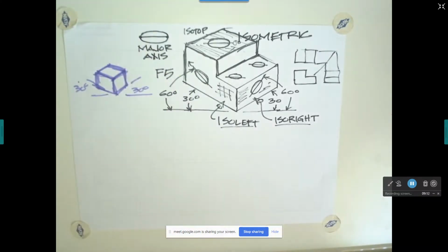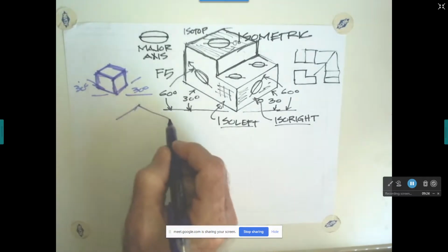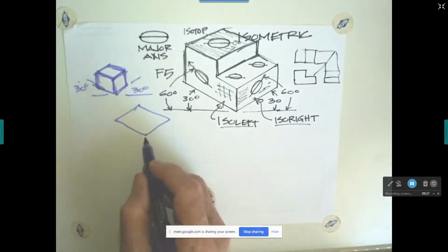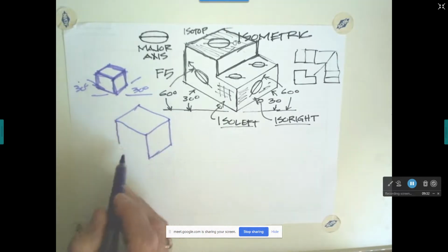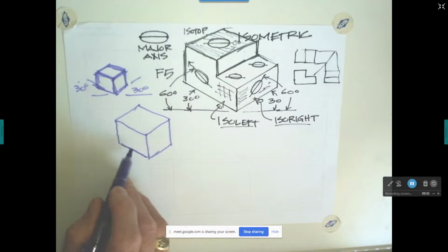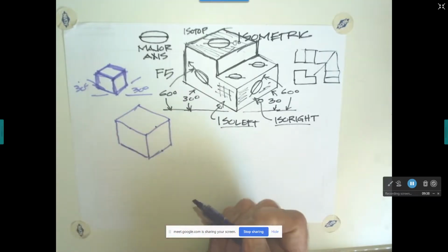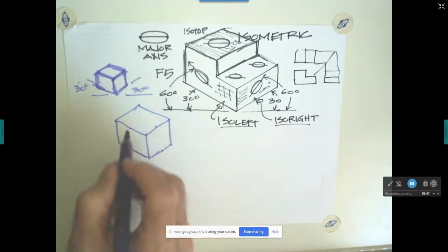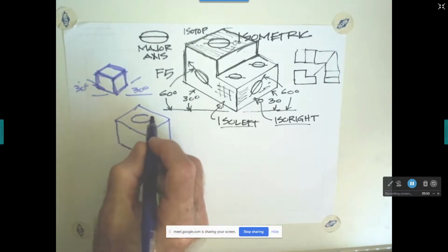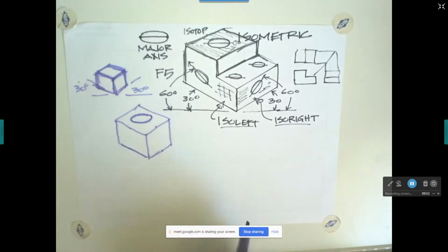And so when I was beginning out, and I knew I needed to sketch, because designers have to be able to sketch, I would just draw this cube over and over. But I'm going to show you something else I would add to that cube. Now, I'm actually going to draw a little bit bigger cube just to make my point here. So draw this a little bit bigger. And remember, this has to be at 30 degrees. And so you want this and this to be parallel, and this line to be parallel to each other. So I would sit in meetings and things like that, just to pass the time while I was listening to what was going on in the meeting, I would sketch this cube, and then I would sketch an ellipse in there on the top surface, like that.